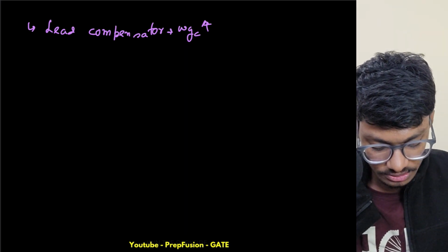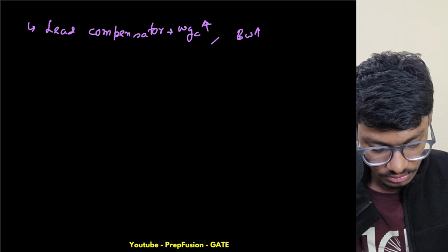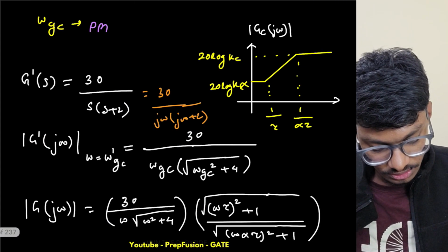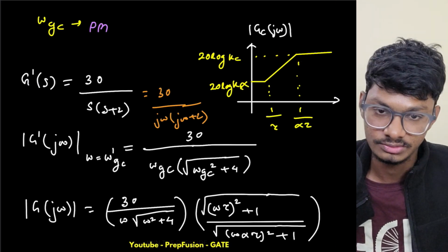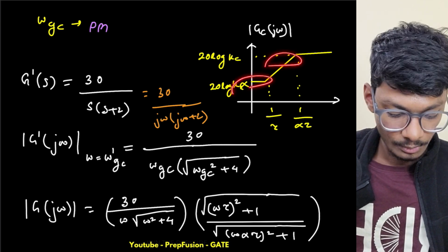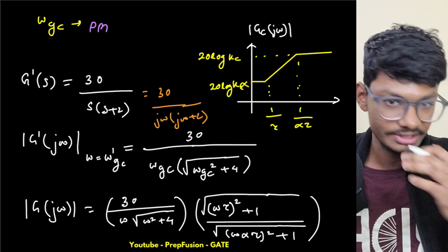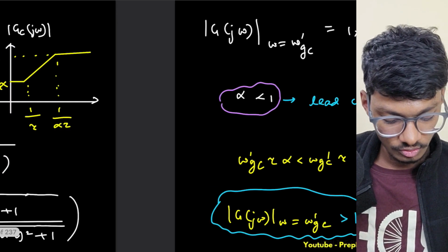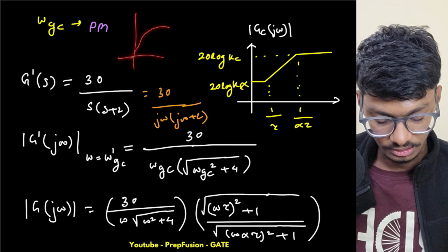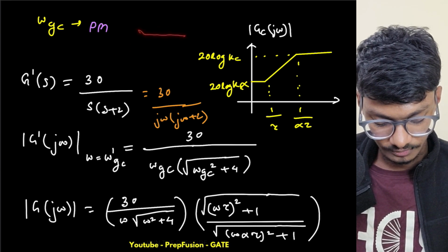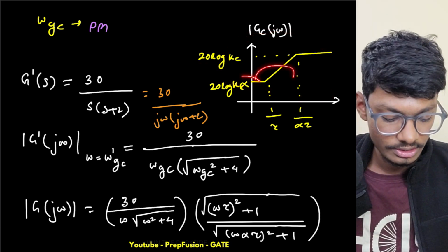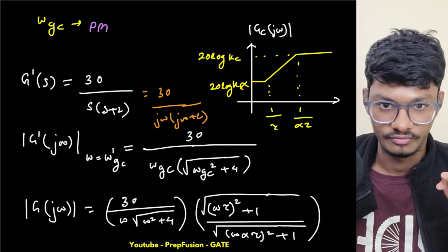How does the bandwidth increase? Because as I can see, it is providing amplification. If it is providing amplification at higher frequencies, at lower frequencies that is fine, it is not doing anything. But at higher frequency, it is providing amplification. So obviously, it is shifting up. Overall, the graph of G of S will be something like this. Let me draw this. If I cascade these two, what will happen? In dBs, it will shift the overall G of S magnitude up.